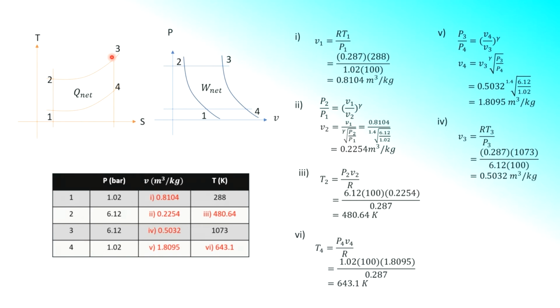So you refer to the isentropic process again, 3 to 4. Okay, 3 to 4, isentropic. So that is why I use this, part 5. This relationship of air pressure and volume finds the volume.